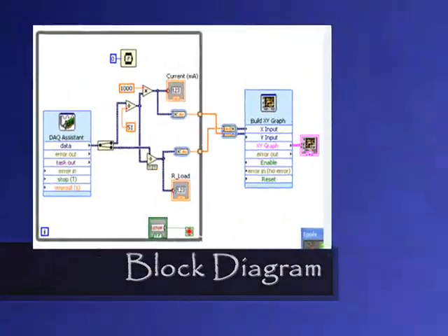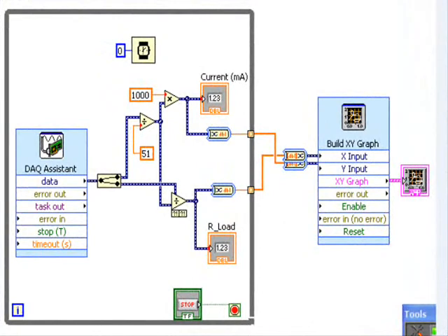Using LabVIEW with the DAC connection, we are only able to read in voltage measurements across potential. However, we need to be able to measure the current flowing across our load. In LabVIEW, the load is indicated here by the resistance of our load. As you can see, we are inputting into it a current which we get by measuring the voltage drop across